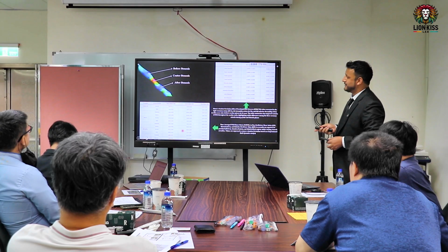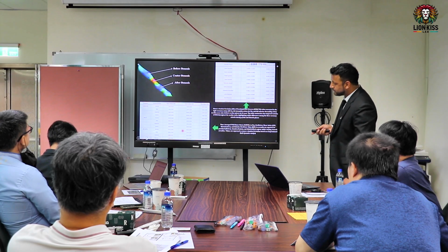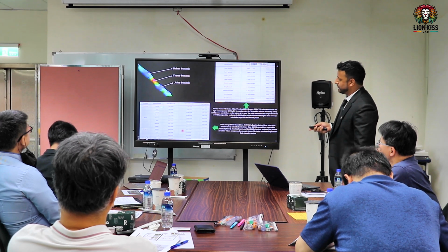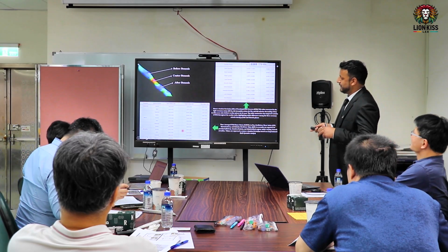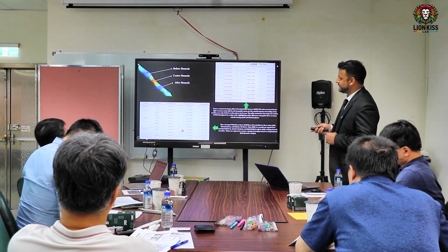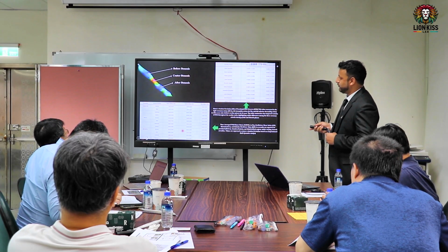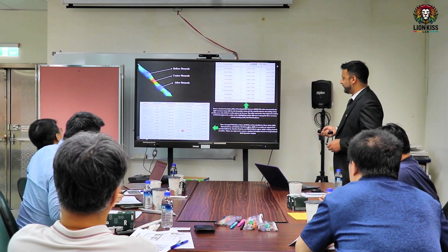And we also measure the same values for TAWSS, RRT, and OSI, for normal, mild, moderate, and severe. So at the center, we see it's increasing with stenosis: severe stenosis is 35.06 and the normal is 5.35. So this one is the time-averaged wall shear stress.